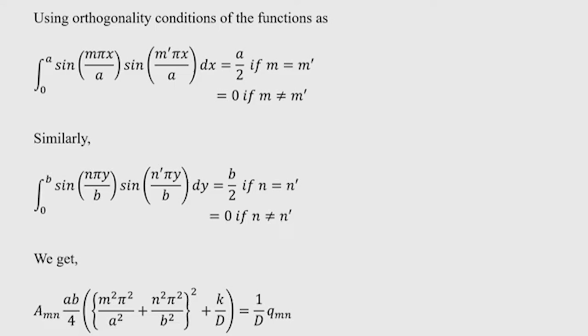So, there will be infinite terms in this series, and we have seen that for deflection only the first term is sufficient for a reasonable result, but for bending moment and shear force you have to consider more terms. However, we get the accuracy with that series, as the series is rapidly converging.